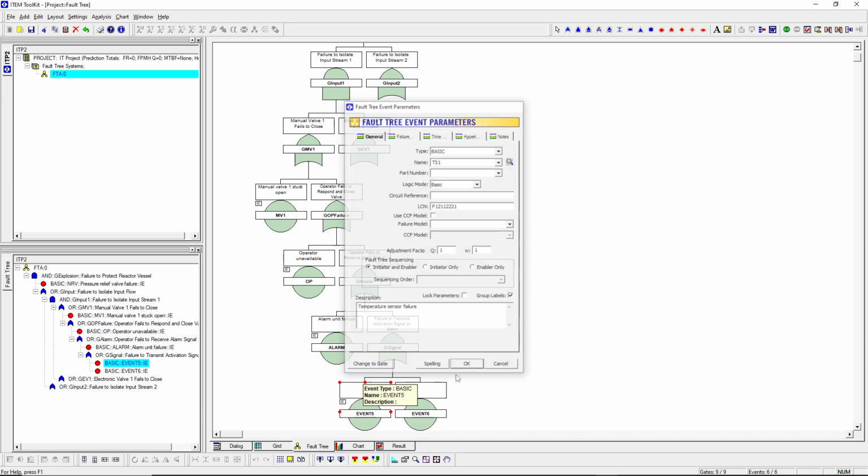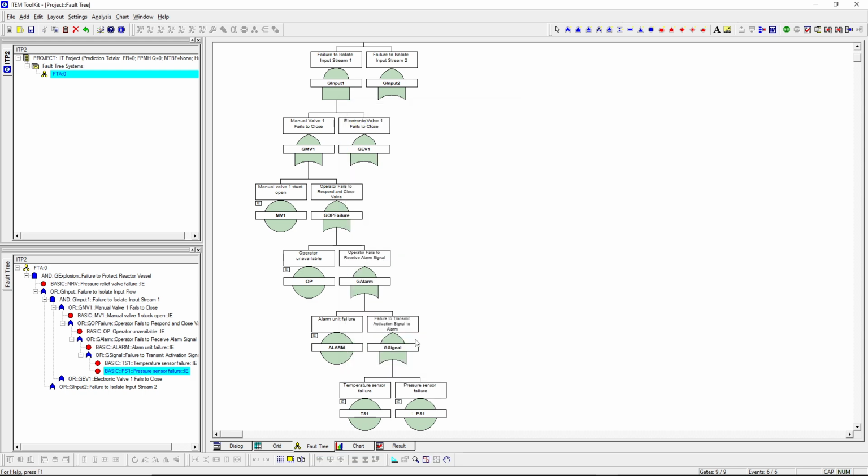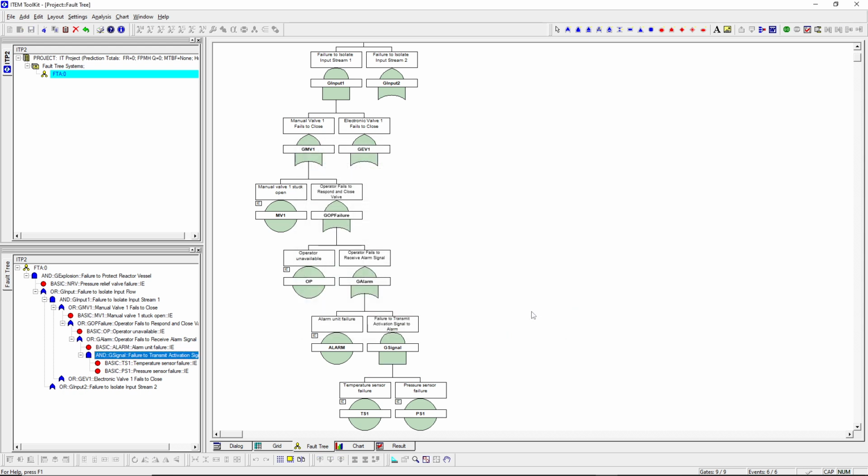To determine the logical type for G-signal, think about how our safeguards are engineered. The alarm is designed to trigger if either abnormal temperature or abnormal pressure is detected. Therefore, for the system to completely fail to send out an activation signal, both sensors must fail simultaneously. If even one sensor detects the runaway reaction and transmits its data, the signal path succeeds. Because both independent sensor faults must occur together to cause a total signal failure, the logical relationship for G-signal is an AND gate. It is a long way down, but we have successfully reached the basic events in this path, meaning we cannot deduct any further.